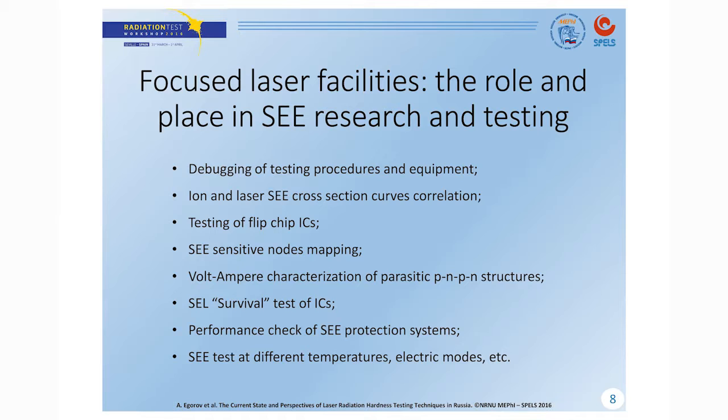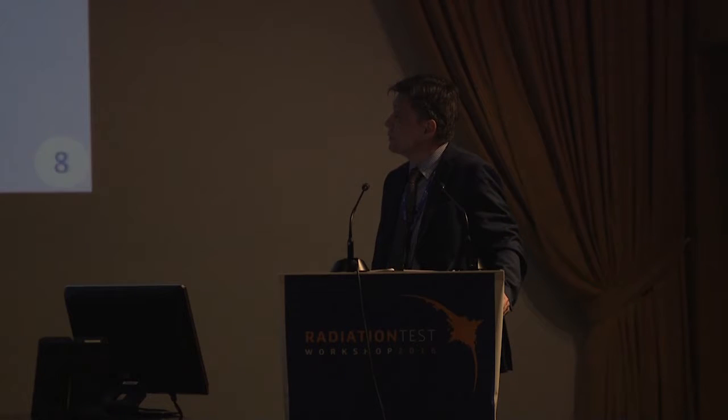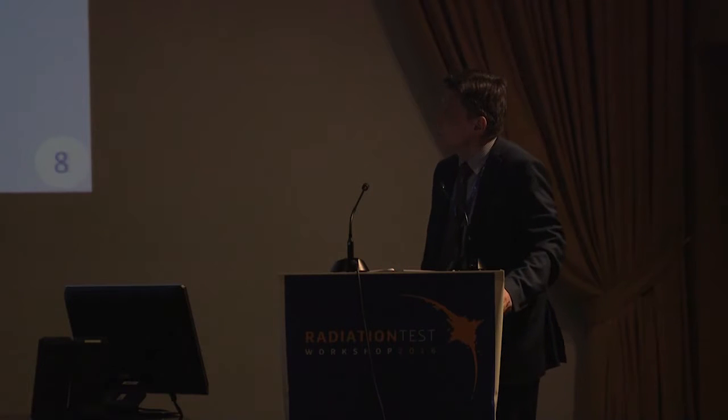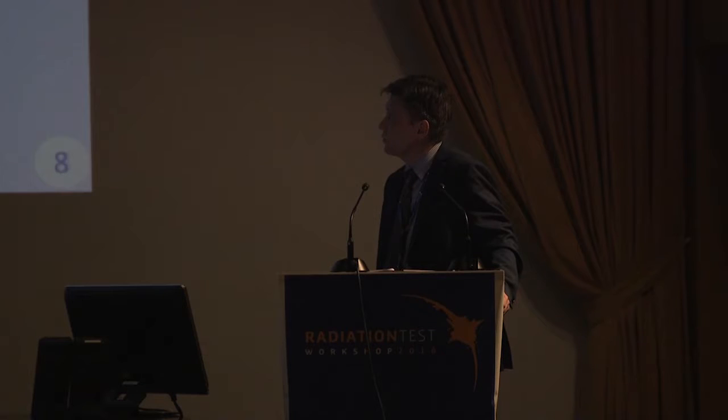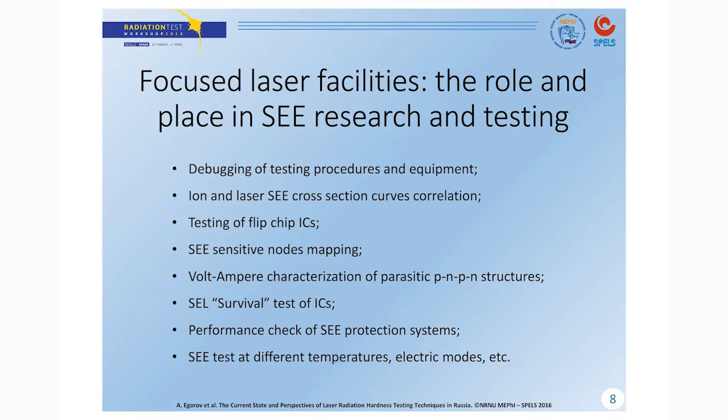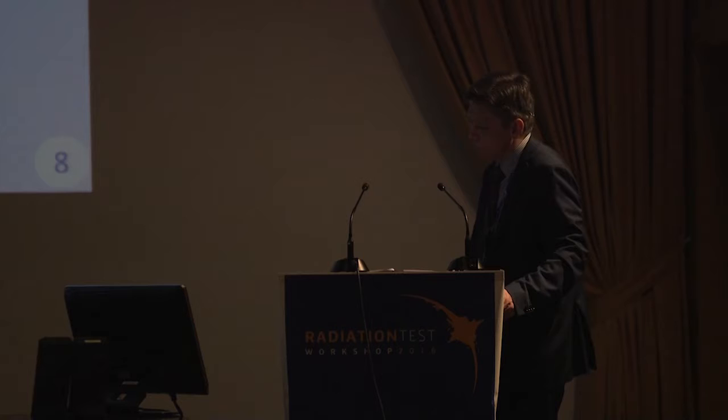The main activities include debugging and testing procedures and equipment, ion and laser single event effect cross-section curves correlation, testing of flip chip ICs, SEE sensitive zone mapping, volt-ampere characterization of parasitic p-n-p-n structures, survival tests of ICs, performance check of SEE protection systems, SEE tests at different temperatures, electric modes, and so on.